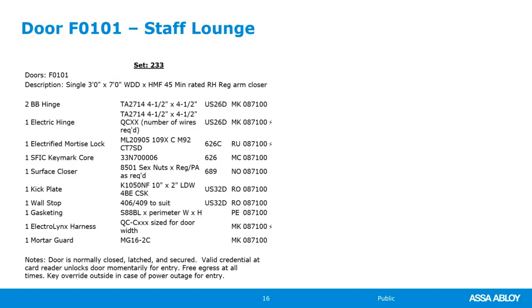The reason that we don't like to use electric strikes on new construction in hospitals, especially high traffic areas or moderate traffic areas, is that when you have a mortise lock, the center line of the latch bolt is not the same as the center line of the strike. And if you're writing a specification and you have 3 manufacturers for mortise locks, let's say Corbin, Russwin, Sargent, and Schlage, and then for the electric strikes, you have 3 manufacturers listed, HES, Von Duprin, and Folger Adam, whatever the 3 manufacturers are.